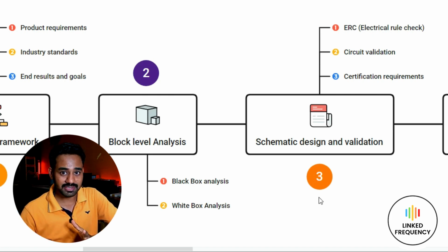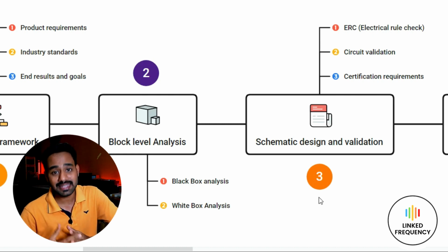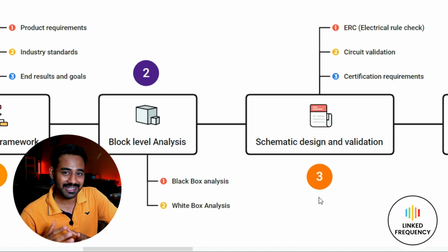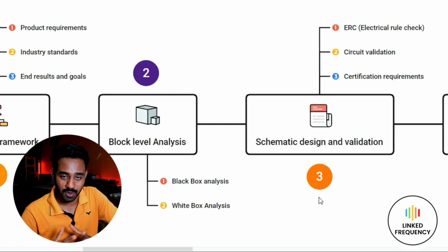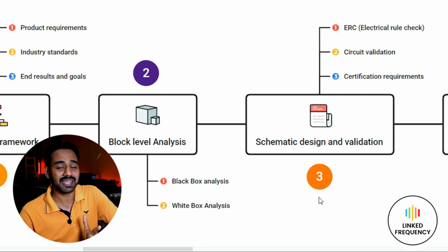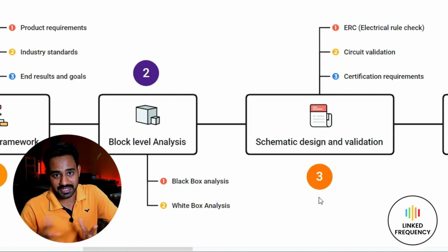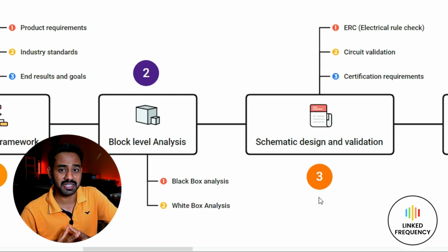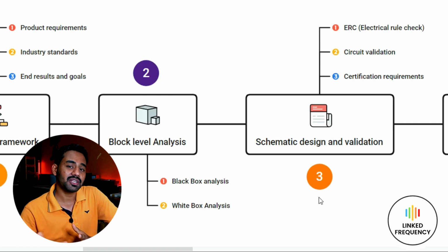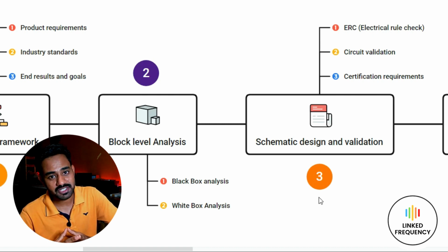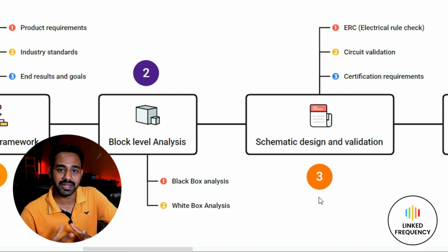Once we have this entire system circuit diagram, we have to identify if there are any errors in that particular circuit. How can we do that? Of course, we can convert that circuit diagram into a schematic by using the EDA tool, which is also called electronic design automation tool. In our company, we are using EasyEDA as an example right now. In that particular software, we are going to convert our circuit diagram into a schematic design.